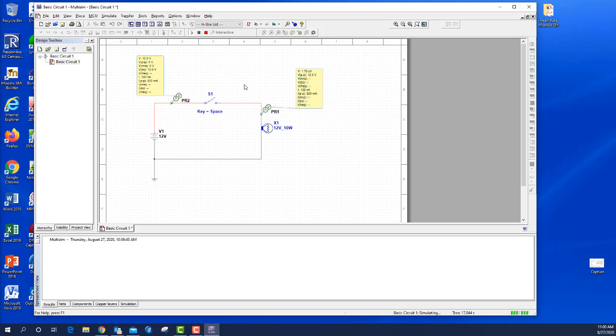And let me press the switch, turn the switch off. And notice that over here, coming out of the battery, we have 12 volts. No current, really. I mean, the current is so small, and that would be what we call leakage current, or just stray current. Nothing of any significance. Same thing over here. We got some stray voltage that's showing up. 1.73 microvolts is too small for a voltmeter to even measure. So basically no voltage at the bulb and no current.